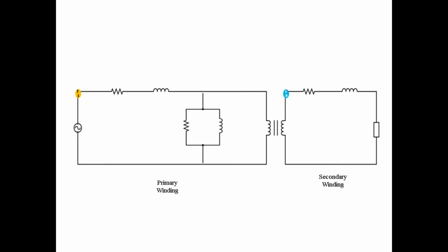The equivalent and approximate equivalent circuits are suitable for constant frequency, steady state circuits. The components R1 and R2, X1 and X2, are the respective resistance and reactance for the primary and the secondary side of the transformer. V1 is the applied voltage and V2 is the voltage across the load terminals ZL. E1 and E2 differ from the terminal voltage as they include the voltage drop across the resistive components.